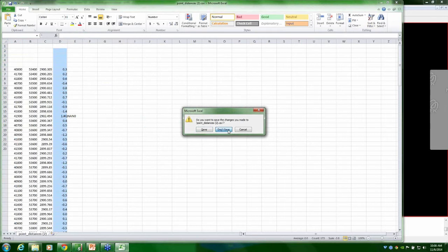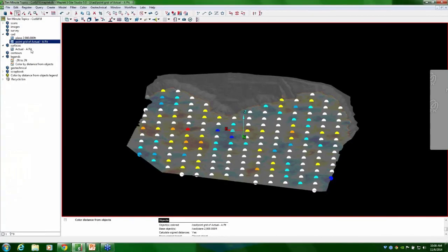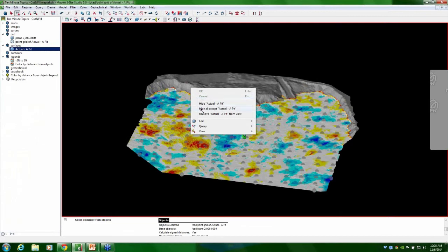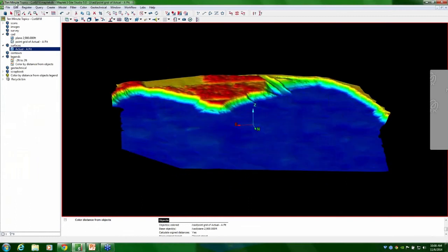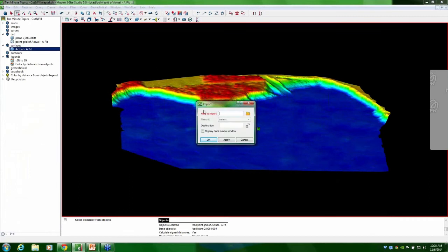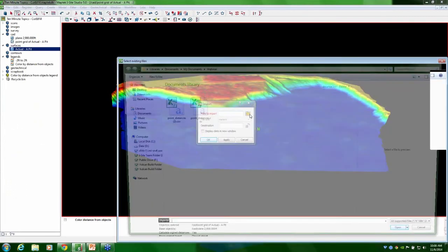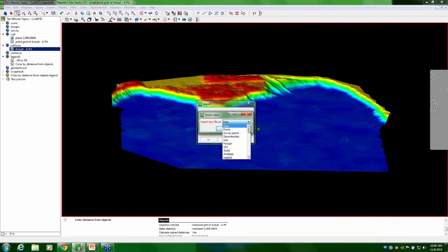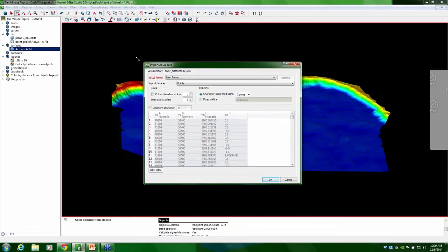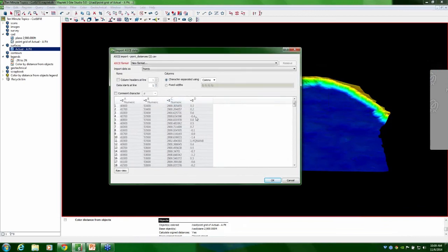Okay, back into Studio. So what I'm going to do here, I'm going to grab this pit. We'll hide everything except that. We'll change the color. And now I'm going to bring those points in. So I'm going to open up my import menu, and then we're going to import that CSV that we just created using a custom import format. If I select that and hit open, I get all kinds of options, a bunch of old ones that I've got saved. But we come down here to custom. This is where having those distances only have 1 point behind the decimal becomes useful.